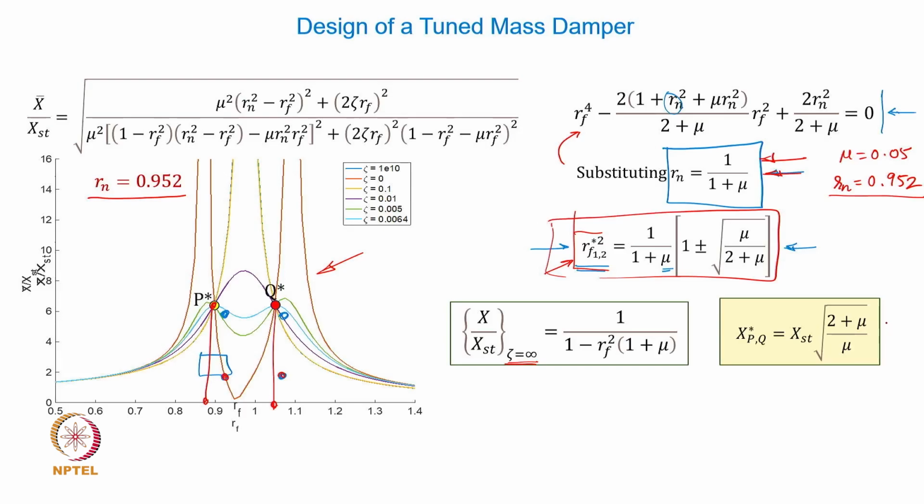Okay, so it so means that once the tuning is done, by way of choosing natural frequency ratios, the amplitudes gets fixed to an expression given by this. That means it again is dependent only on the mass ratio, as we have found from this expression.